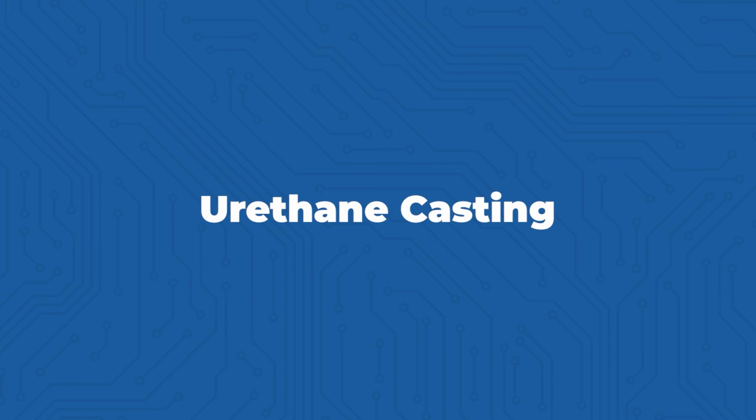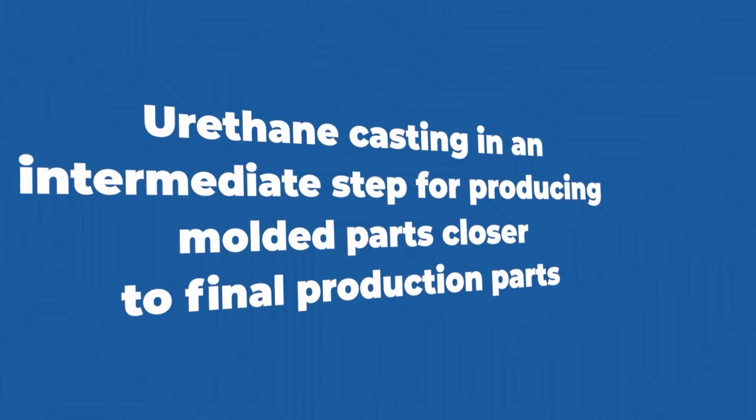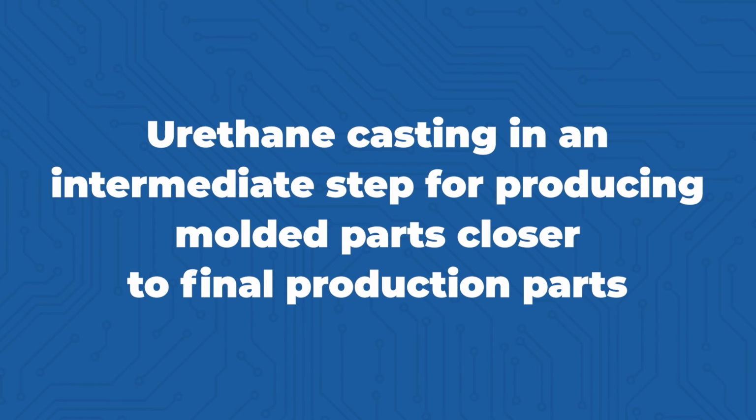You don't want to have to do injection molding because that's going to have a really expensive upfront cost, for the cost of the molds. Urethane casting is a nice intermediate way of getting molded parts that will look closer to your production parts and have the same finish as the production parts, but yet they don't have the complicated or expensive mold requirements.